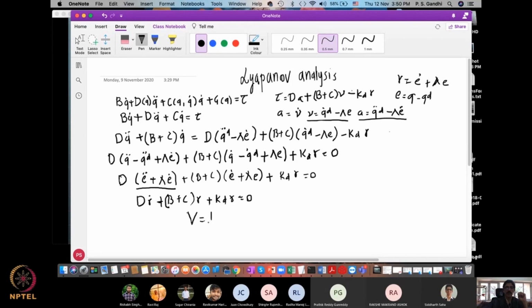V as half. When I take a derivative I'll need this d r dot to be substituted, and d we know to be the inertia matrix, so I can use d as the inertia matrix here. But instead of the error in terms of e and e dot, we can consider this in r terms, so r transpose d r is what I consider as the energy function.